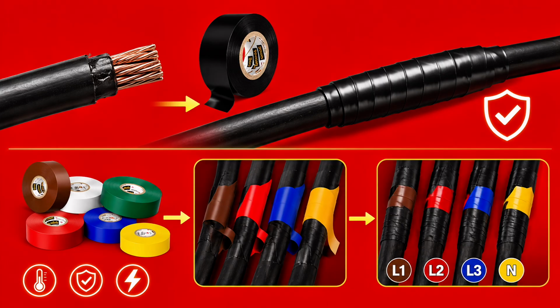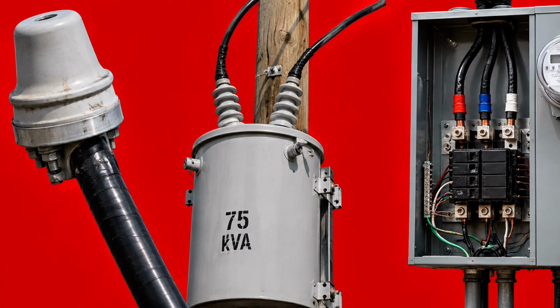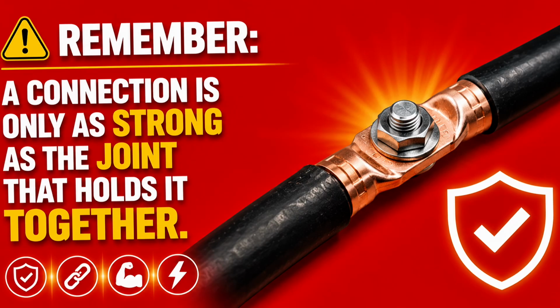After re-insulating the conductors, phase identification tapes are applied to restore the correct color coding and ensure phases can be easily identified. This is a common maintenance practice at potheads, transformers, and service entrances. Proper crimping tools, approved connectors, compression lugs, and suitable joining methods must always be used. Remember, a connection is only as strong as the joint that holds it together.